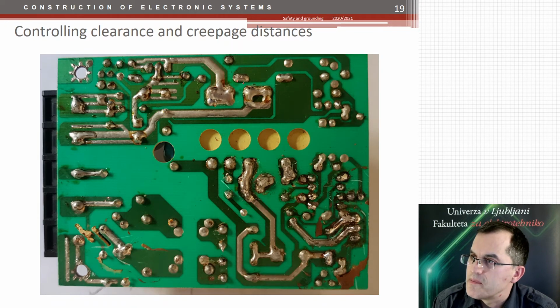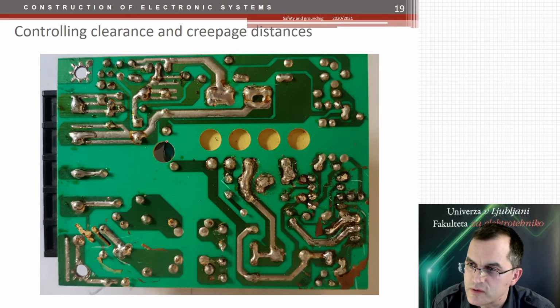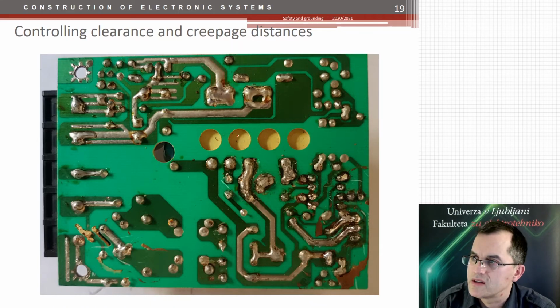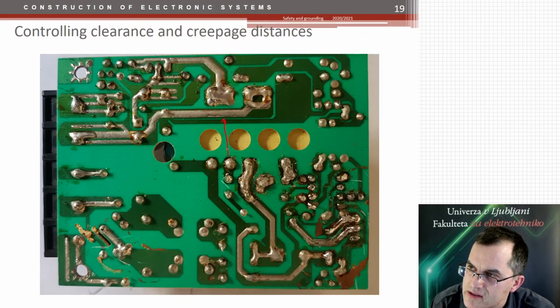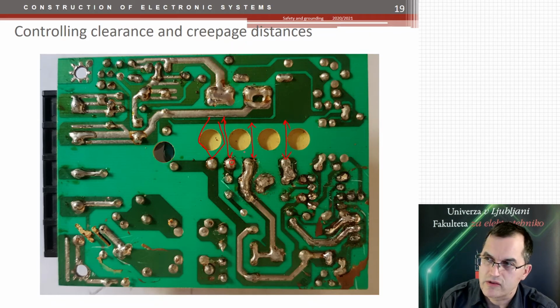For example, here is another example of a power supply that has some cutouts for increasing the creepage distance. You see that these cutouts are not very well made, because the creepage here is not changed at all, because this gap should be continuous. So these openings here do not help increasing the creepage distance for that connection here. It may help increasing it for that one, or maybe for that one not that much, actually up to here. So I must say that this example is not a very good one for increasing creepage distance.